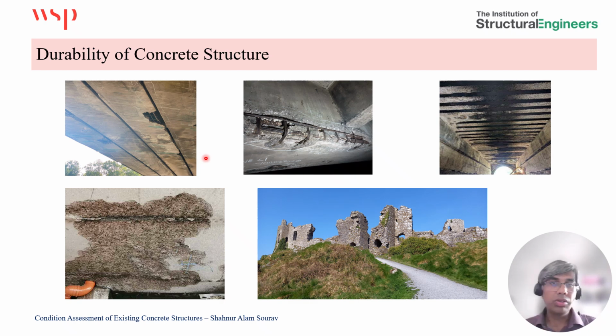Here are some photos of durability issues that I have encountered in my work life. The top left photo shows concrete spalling and exposed reinforcement in the beams of a bridge which has been affected by vehicle impact loading.